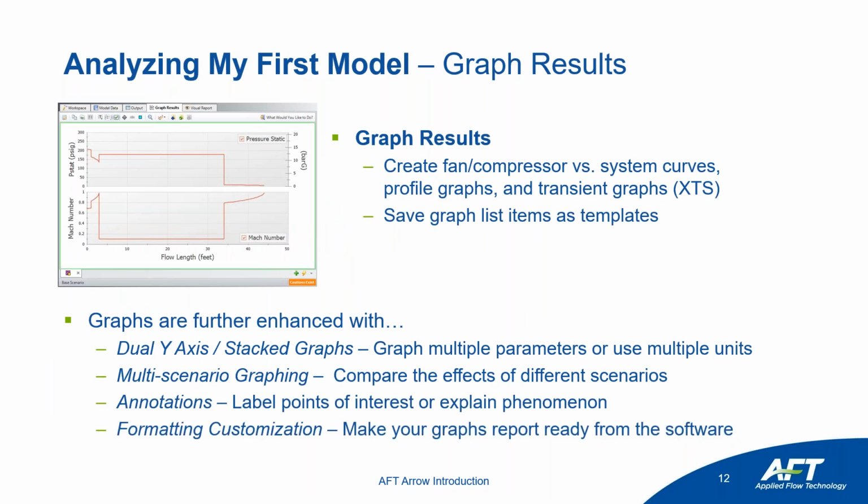So we saw both dual y-axis graphs and stacked graphs. So dual y-axis, that could be different parameters, or here in this example, we have bar G on the right and PSIG on the left. You can graph multi-scenarios. Again, we'll touch on scenarios here in a moment. You can also add annotations, maybe labeling where your control valve or your orifice is.